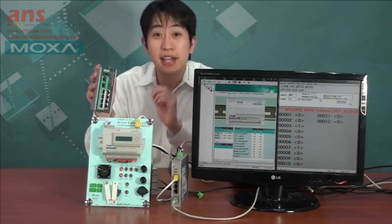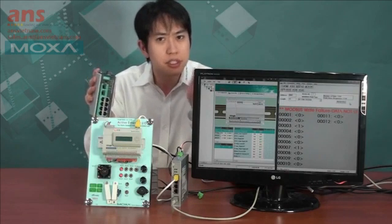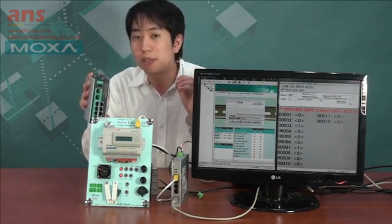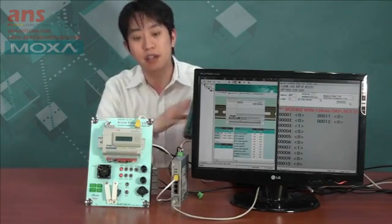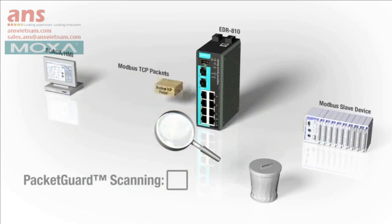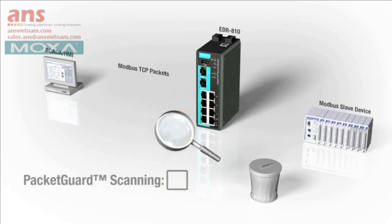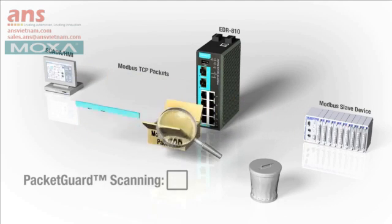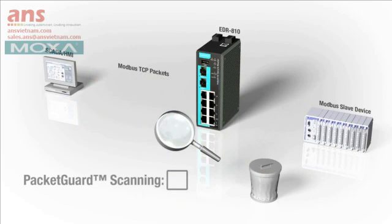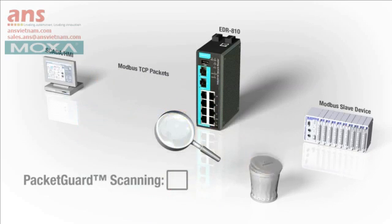Now, the EDR-810 has a built-in firewall and VPN functionality. And critically for industrial networks, it also adds deep scanning of industrial ModBus packets, what we're calling PacketGuard. PacketGuard performs deep inspection of every individual ModBusTCP packet and verifies its slave ID, function code, and register address. ModBus packets that do not meet its requirements are dropped. This adds one more layer of protection on the application level to an existing firewall.